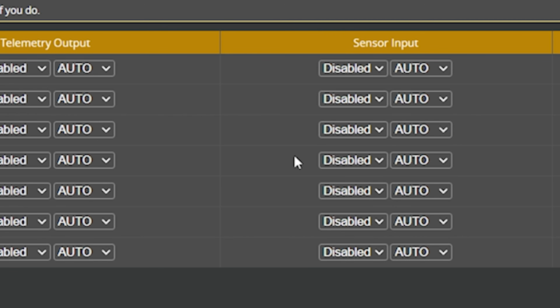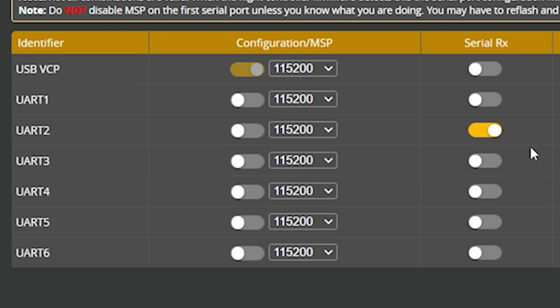Instead, it just completely wipes the whole Ports tab clean, and that's why I told you in video number 1 to back up your configuration before you start working on this, because you could get it back. So you can only have one thing at a time on each row, on each UART of the Ports tab. There are a very few exceptions to this. I want to acknowledge that they do exist, but they're very, very rare, and almost always you'll just wipe your Ports tab if you try to do two things on the same UART.